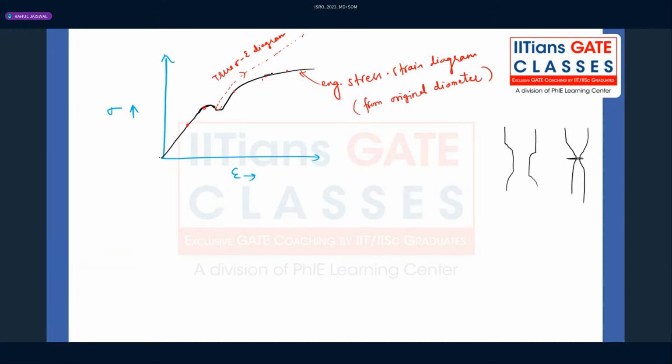So here, whatever you are assuming, we have to reduce the load to get the maximum fracture point, right? That is why the curve is getting flattened. In some cases you will observe the curve actually decreasing. Stress will be decreasing, but generally it won't happen in reality. In the true stress strain diagram, it is actually increasing because the area keeps decreasing, and stress is load divided by instantaneous area. So as the area starts decreasing, the stress starts increasing at a very rapid rate.